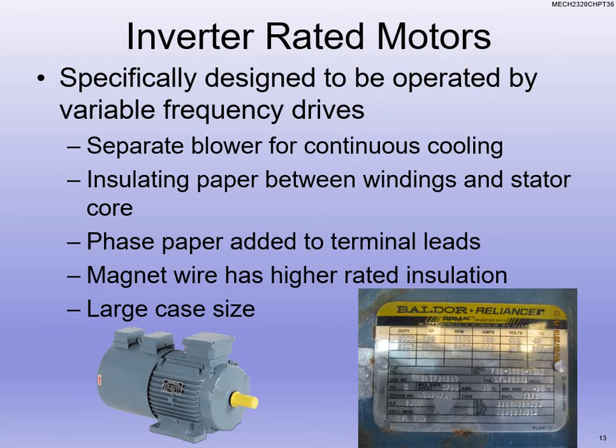Okay, so next there's special motors that we can buy that are specifically designed to operate with VFDs. They're called inverter rated motors. They have a separate blower on them so that you can continuously cool them. Notice there are vent fans on it. This is a picture of one, what it would look like as well.